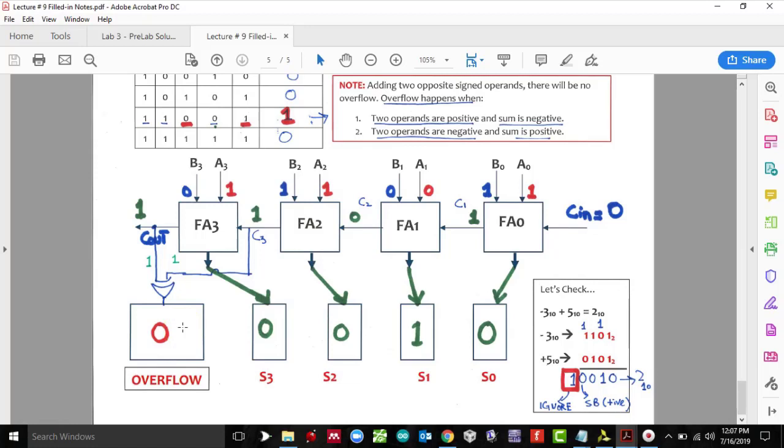Okay, so the first thing that we need to do is come up with an expression for a 7 segment, which will take S3, S2, S1, and S0 as inputs, and then display it on a 7 segment in decimal. The second thing is to come up with 1 full bit adder, and then create 4 of them by instantiating that full adder. Lastly, we are going to put the system together in our top module and see if we can get it to work.